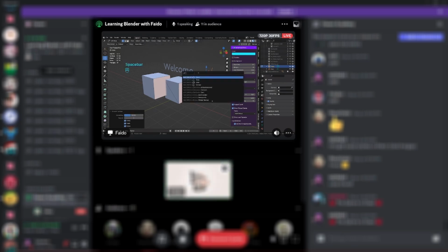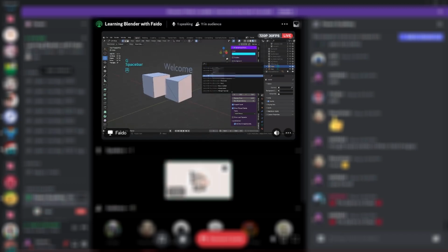I forgot to mention that when you first open up Blender, a screen will pop up asking whether you want left click or right click. I changed mine to right click as the selection because I'm used to it, since different programs have different things. And spacebar to search bar.